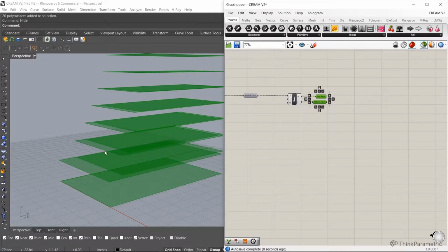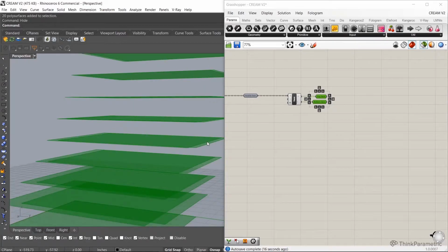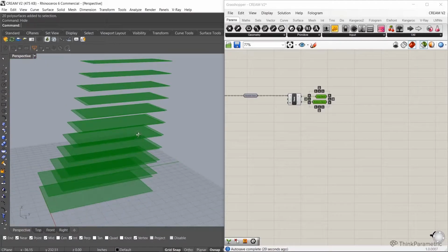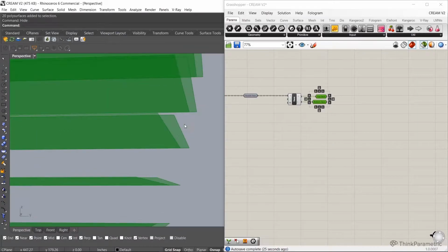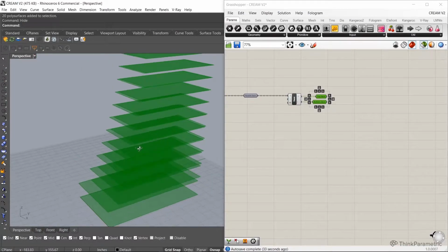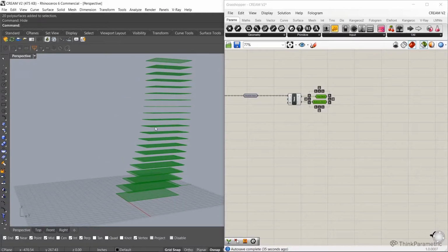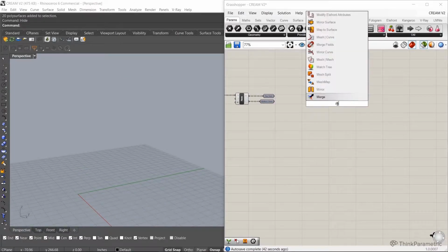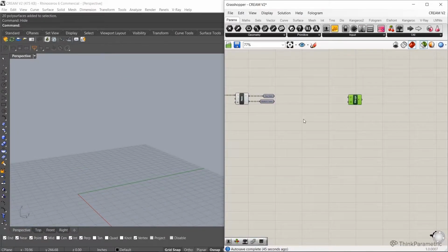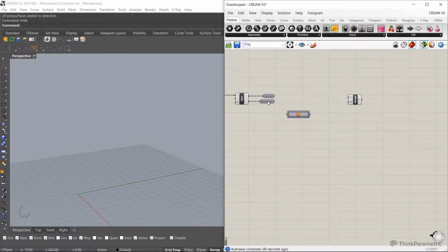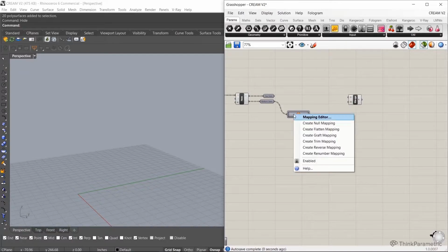We're going to use these to create our floor plates, but the one tricky thing is that our floor plates are not super simple, because you can see they're overlapping. In some cases we have what would be a balcony at the front, and a kind of overhang at the back. So we need to do a little work to join these together. It's not going to be too tricky, but we need to union these so that we can create our floor plate outline. The way we're going to do this is grab the Merge tool.